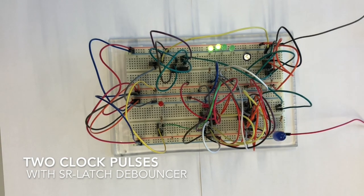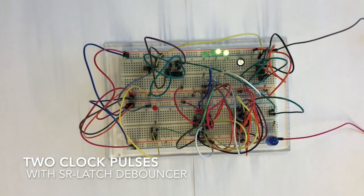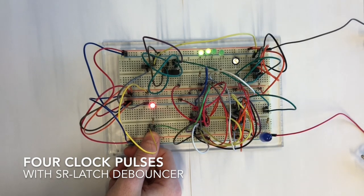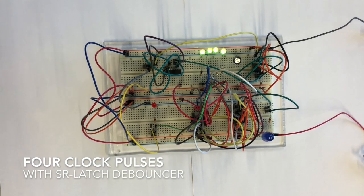When the button is pushed very quickly, nothing happens. This is because the push button and the rising edge of the clock have to meet at the same time. For every combination of button pushing, we got the output shifting 1 bit at a time, which is the expected function.